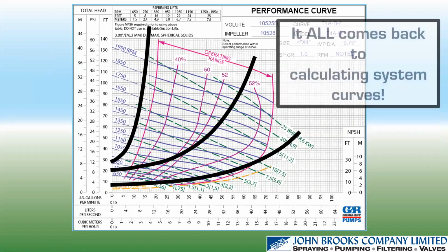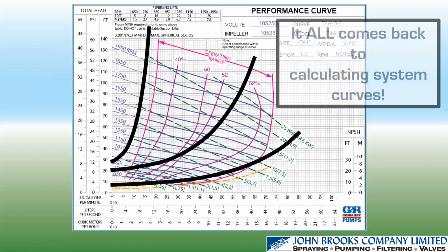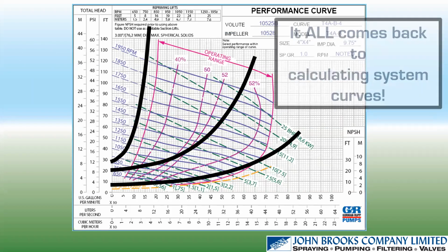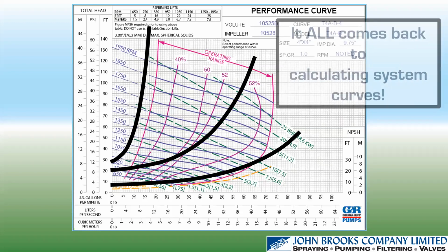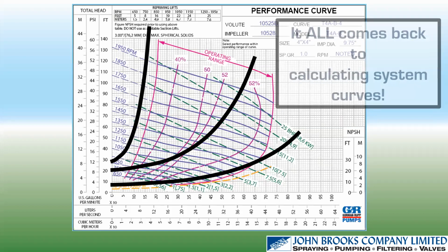And what does it all come down to? Pumps are important, but I always think system curves are more important, because without a good system curve, you don't know where this pump is operating. You could be operating on the left-hand side, in the middle, or over to the corner. You can buy the most expensive pump in the world, but if you don't have a good understanding of system hydraulics, you're just throwing your money away.